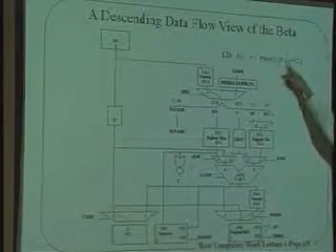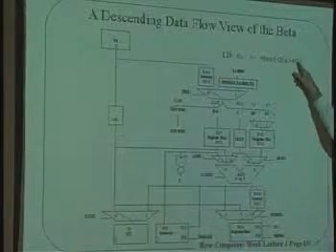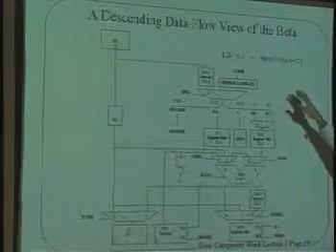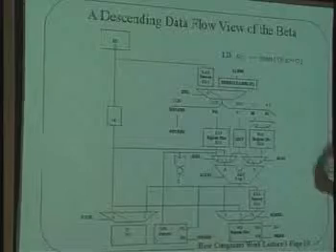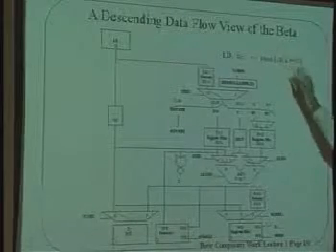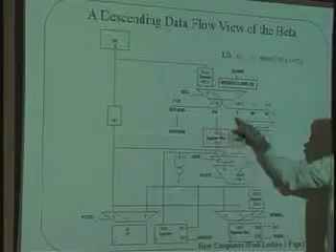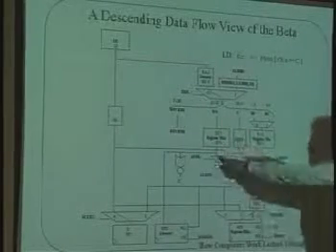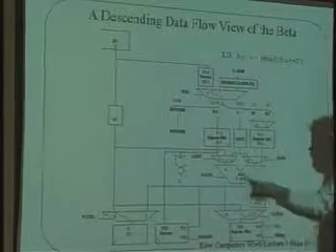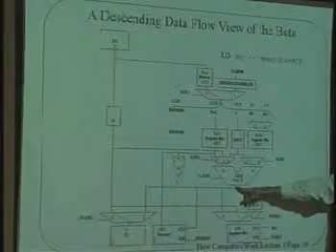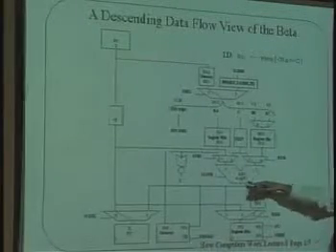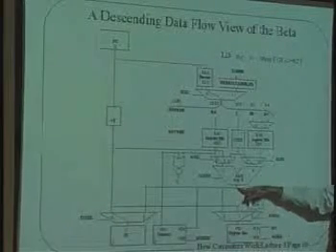What do we need to do? We need to find the contents of RA, and we need to add C to it. In that way, it's very much like one of those standard arithmetic operations that's taking the contents of RA and adding C to it. And so the instruction comes in here, it gets put out, we take RA and C, steer them to the ALU, do the add, and what pops out of here is the contents of RA plus C.